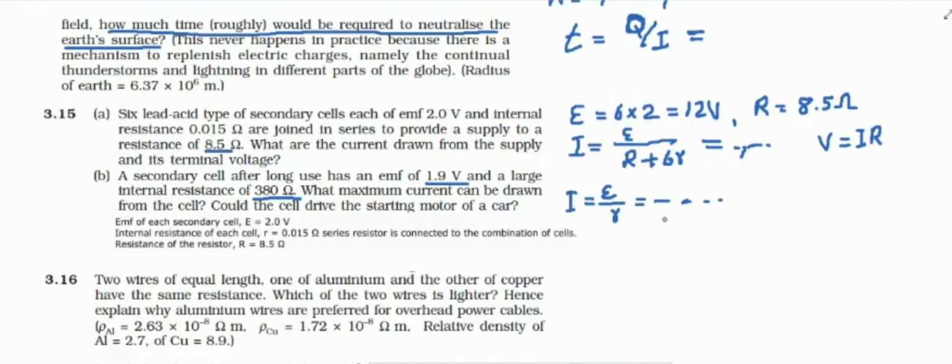What is the reason we need to use a bulky car battery? The reason is that acid batteries have very less internal resistance. Small r will be very small. So we need more than 100 ampere current to start a car. Initially we need a very high current.